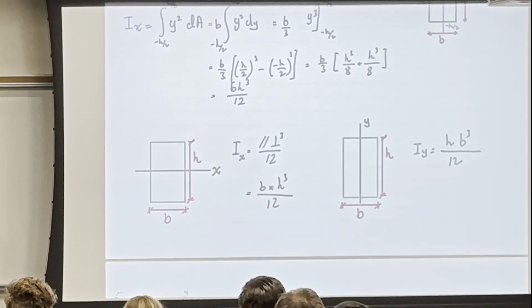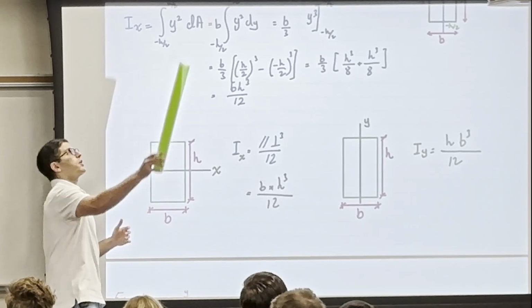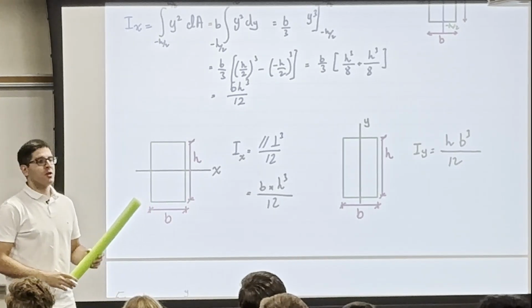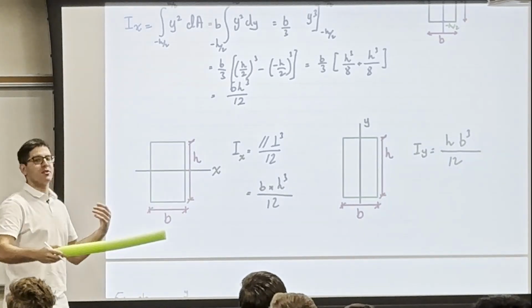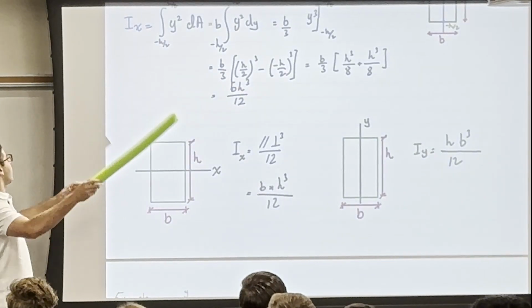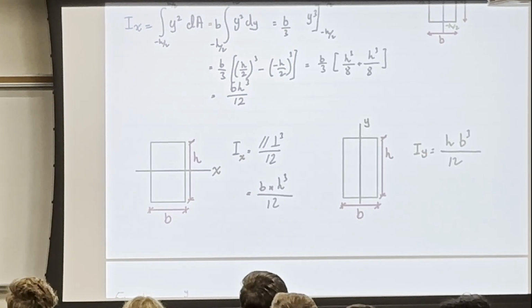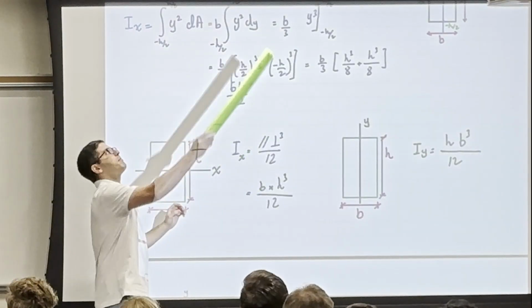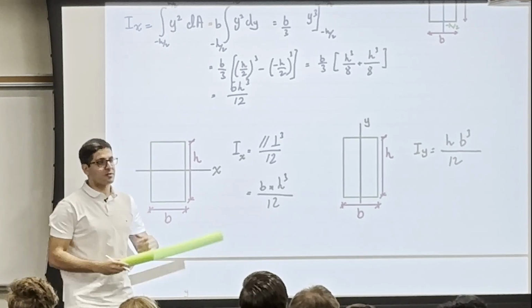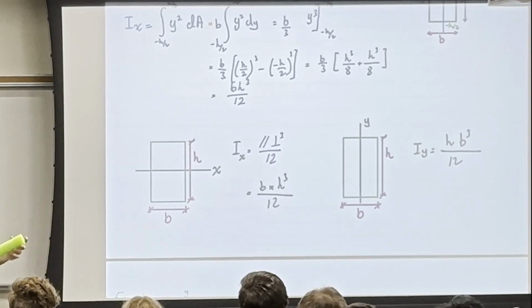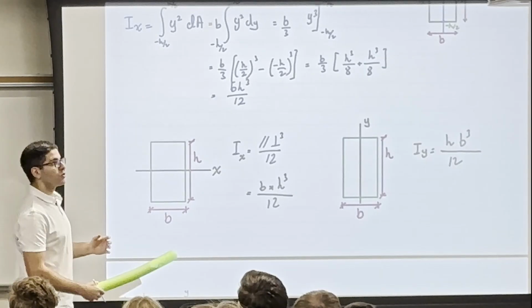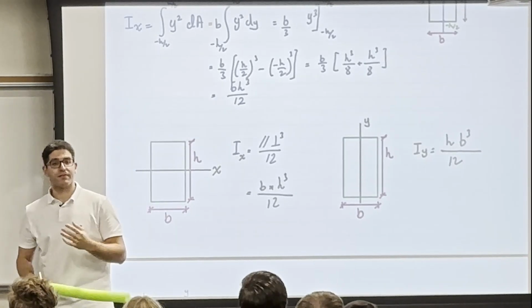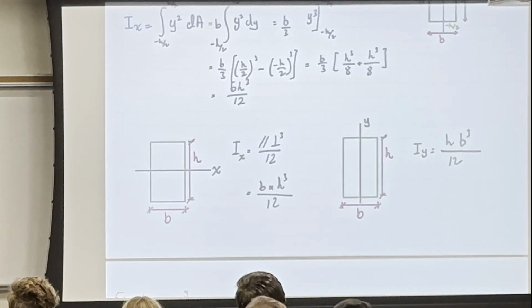But sometimes the architect, and it does make sense, I want to increase the stiffness of that beam, but I can't increase the h forever. Because you guys are going to be disturbed and the architect is going to be disturbed, because it's going to obstruct the view of the board. That's why sometimes you'll find a beam with a very large width. That doesn't make sense, but again, we have no choice. There is nothing to do but to increase that width. So if you have the luxury to increase the height, you're going to get more stiffness, but this luxury is not always there. You always have a limit.